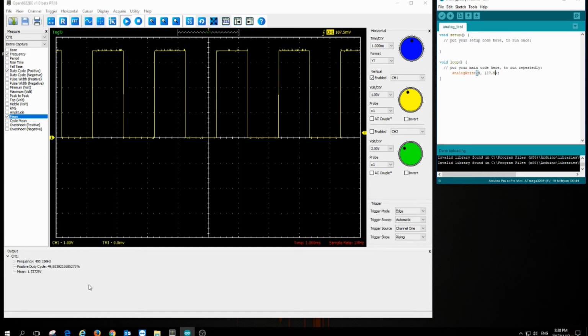So now what we're going to do is make that PWM actually do some work by driving the gate of an N-channel MOSFET, so you guys can see how that can be used as a power control device. Because bearing in mind, this is only digital signals. It can't control high voltages or high currents or anything like that without some sort of a buffer between the two. And we're going to use a MOSFET as a stage 1 buffer.